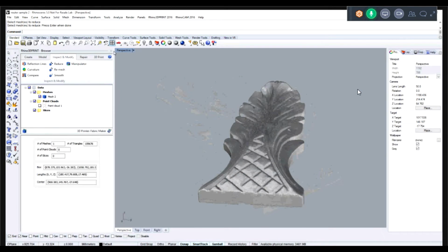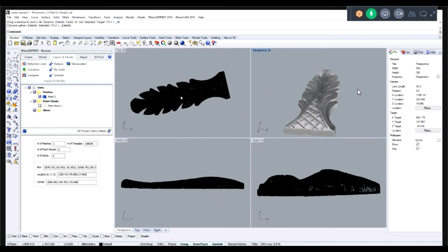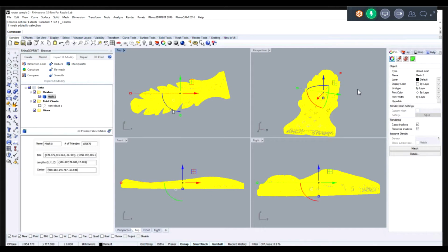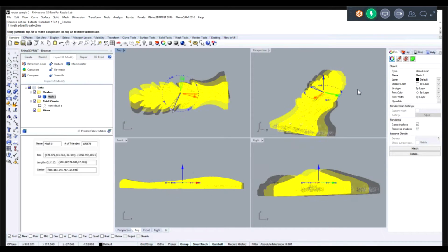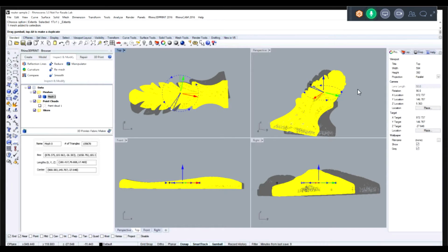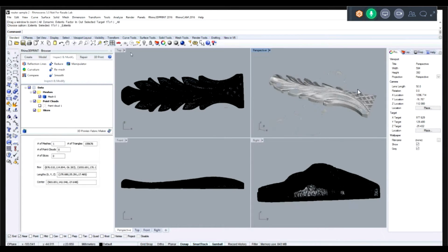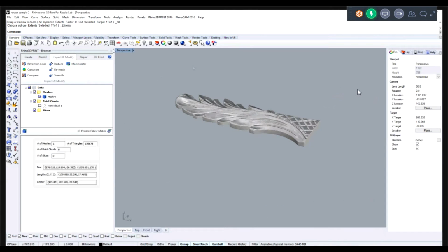Now, once this model is ready here, you can go to the process of machining it here. So if you need to rotate the model to line it up, I can use the commands in Rhino to line it up right there. And we can go into RhinoCam for machining it. So you just go to RhinoCam and select your mill browser and generate your toolpaths.